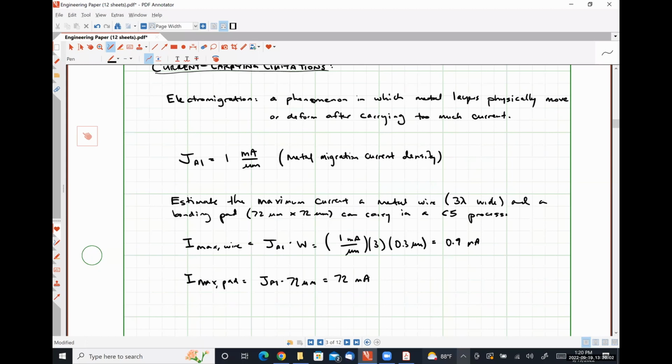You cannot effectively embed your bonding pads down at a lower layer and then try to make a deep channel through several layers of silicon dioxide or whatever type of insulation you have. It needs to be as close to the surface as possible. And then you would use vias and contacts to get your signals lower down to the actual transistors or whatever you have in the substrate.